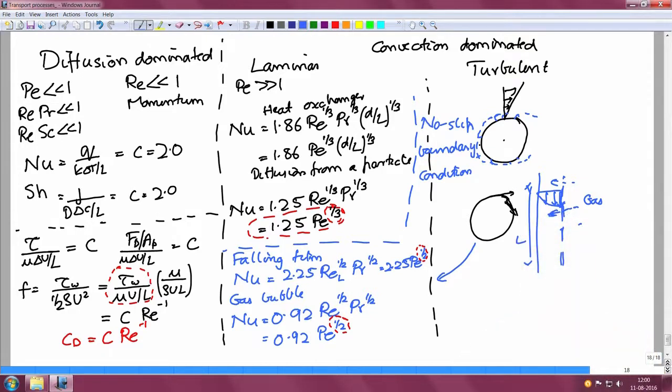And because it is restricted to thin regions, the gradients are much larger there than you would expect, therefore, the transport rates are much larger. And because convection is dominant, the nature of the flow close to the surface is important. And broadly, the kinds of flow can be divided into two broad categories. One is when there is a solid surface.